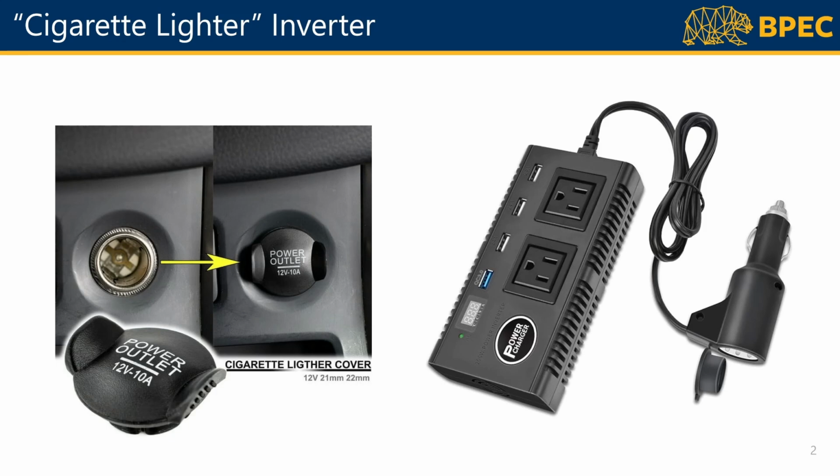So you plug this in, and it converts that 12-volt DC input to a 120 volt RMS AC output voltage, and this is meant to emulate a fake grid. So you could plug your devices, like laptop chargers or phone chargers, into these outlets, the output of the inverter, and use it like you were plugged into the wall, only when you're in your car.